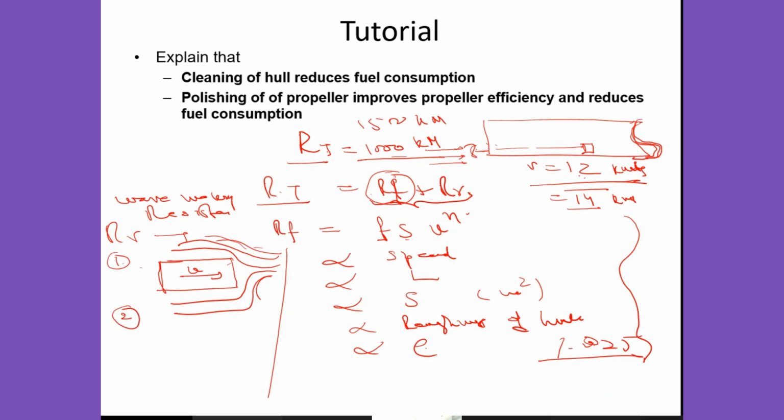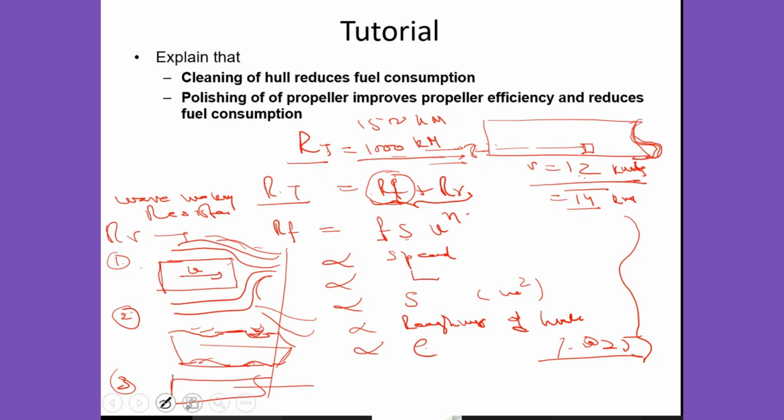The second component is the formation of eddy currents. If you have a change of cross section in the profile of the vessel, let us say, to make it clear, these are the eddies where you have the change of cross section anywhere on the profile. So that streamline is another thing. This is eddy current formation, the second component of residual resistance. And third is, as the vessel moves, you have the waves created. This energy also comes from the ship's engines.